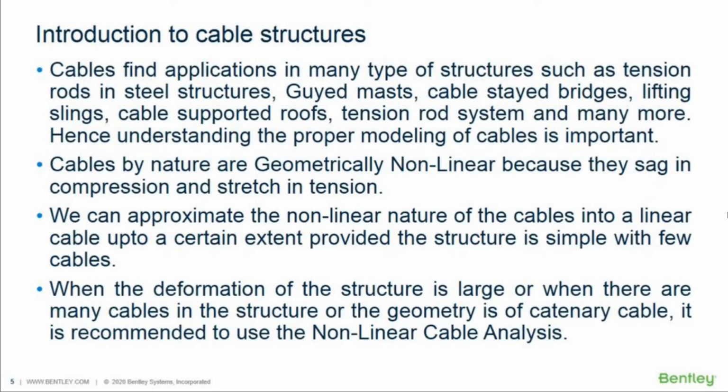When the deformation of the structure is large, or when there are many cables in the structure, or if the geometry is of a catenary cable, it is recommended to use the nonlinear cable analysis. Okay? So these are the three cases